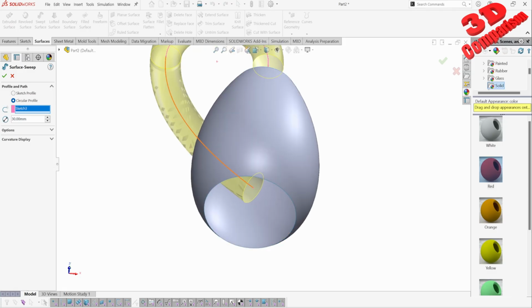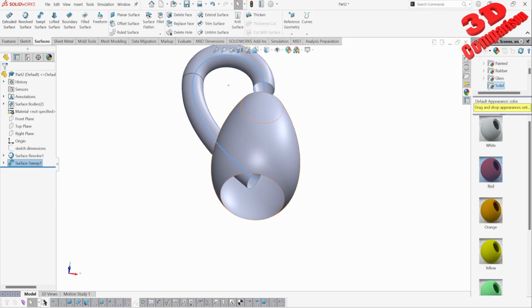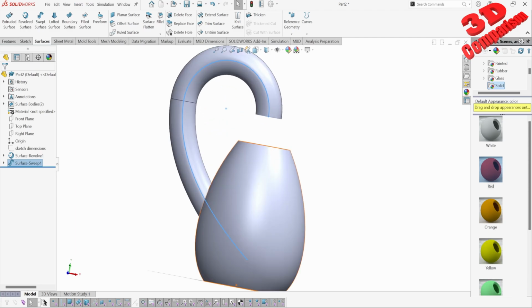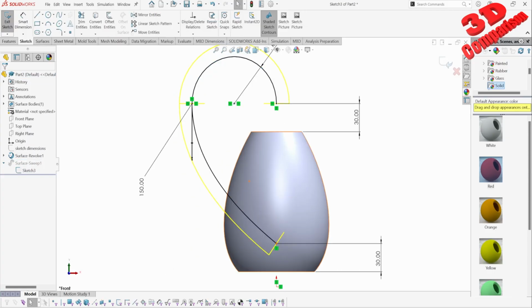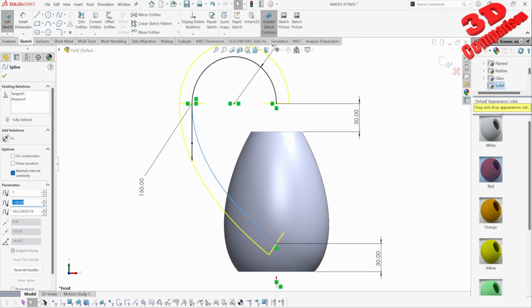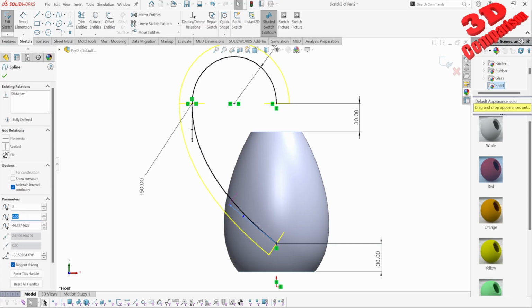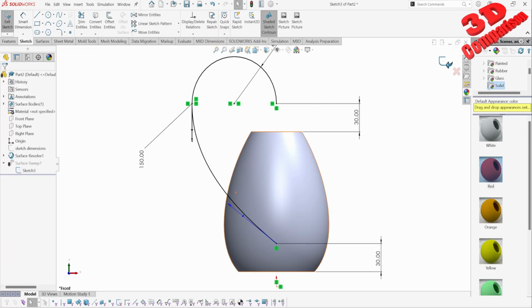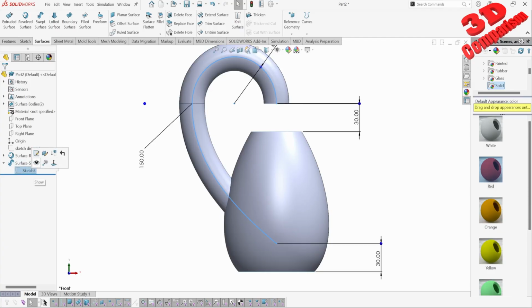We see over here that where this will end, it will be at an angle. So I should adjust that, because over here on the bottom we need to have those just like over here. So the bottom section with this one should be parallel. Therefore I will go within that sketch, and over here for this arrow, select the spline, select the arrow. Let's see, I should be able to add over here that vertical. I will just leave that sketch so we have that defined.